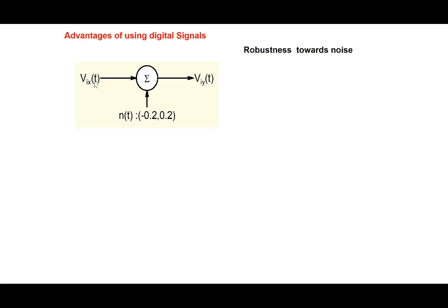We mentioned briefly that almost every electronic component, every resistor, every diode, every transistor, they're all sources of noise. And then the power supply we have seen may have some ripple, and ripple is unwanted. So that's also a noise, an unwanted thing. And there are various environmental sources of noise. If you have imperfect switches, when you switch something on and off, those switches also radiate noise, and the noise can then get into your circuit. So there are various sources of noise.